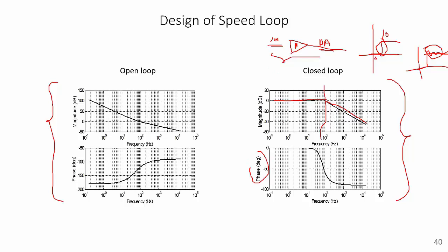And the second plot is the phase plot. So again, as long as it's within the crossover frequency, you want the phase of the system to be absolutely zero. So whatever is in the input is reflected at the output. So that means, say, if I have a very low frequency sine current that is desired to be generated, the output would still be the same low frequency current with a magnitude of 10 ampere. And the phase difference between the reference current and the actual current would be zero at very low frequencies. And once you reach high frequency, the closed loop system is effectively a low pass system, so it is going to reach a phase of minus 90 degrees.